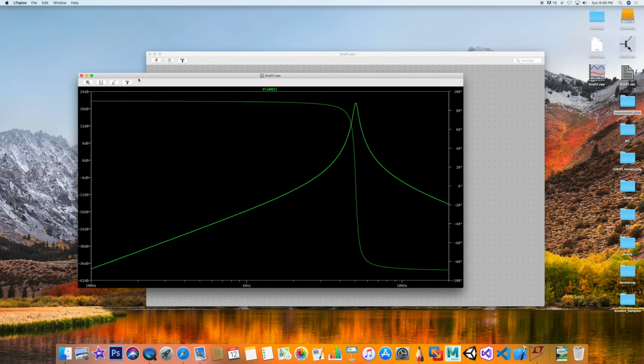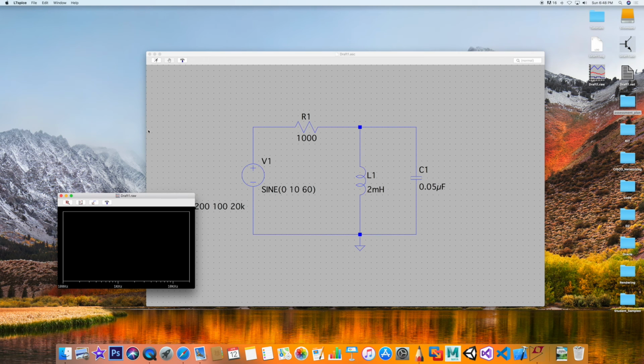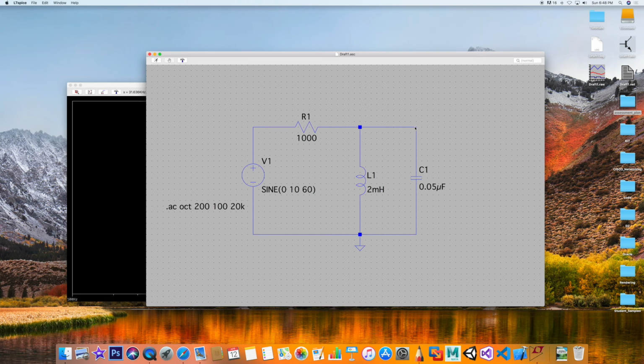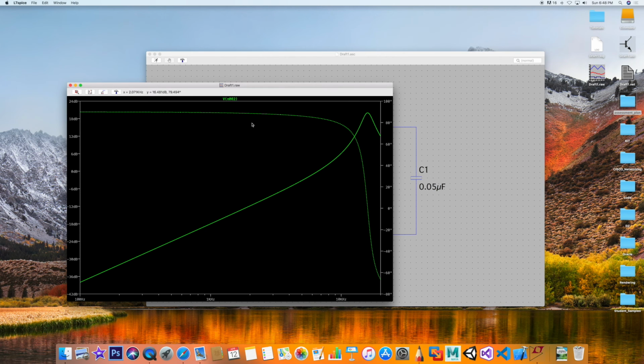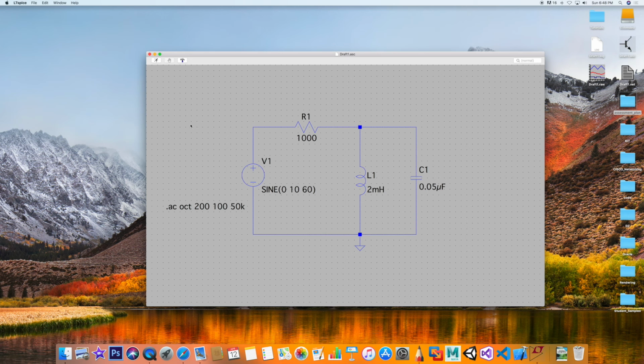I may have to increase the range in which I measure my spectrum here. So again, be flexible. Find out if indeed that's what you want to do to view where you're tuning. So if I click here, let's see if it's out right here. As you can see, I'm reaching the end here. All you have to do is increase the range or the bandwidth in which you're observing. Remember here, we had 20K. We could change that to 200K or 50K. So I'm going to change it to 50 kilohertz. Hit enter, and let's see what we get. So I'm going to run this.